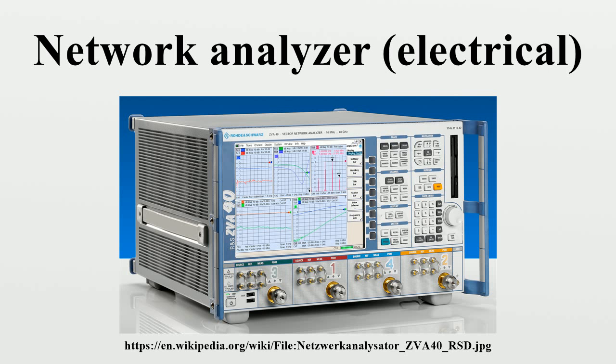RxREF1, RxTEST1, RxREF2 and RxTEST2 are known as coherent receivers as they share the same reference oscillator, and they are capable of measuring the test signal's amplitude and phase at the test frequency. All of the complex receiver output signals are fed to a processor which does the mathematical processing and displays the chosen parameters and format on the phase and amplitude display. The instantaneous value of phase includes both the temporal and spatial parts, but the former is removed by virtue of using two test channels, one as a reference and the other for measurement.